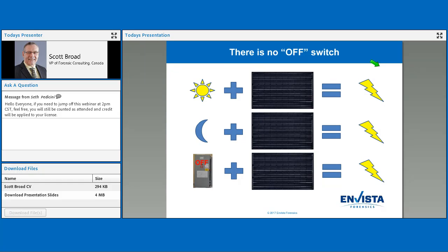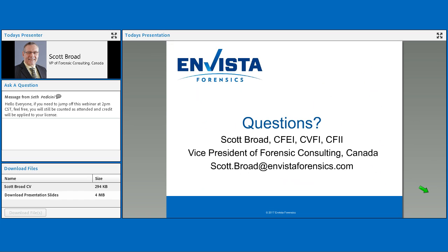Right now, there's a question here: is there a requirement for periodic IR scanning? Right now, I know that the National Electric Code is looking at several code changes that will include such. They're also looking at safety systems. If we do have a rooftop fire, what we noticed in Ontario originally was the fire department would show up and have no idea what to do. They didn't know, could they put water on it? Could they turn it off? They would go downstairs and turn off the master switch, but not understand that the panels still generated power. How do you attack them? What do you do?